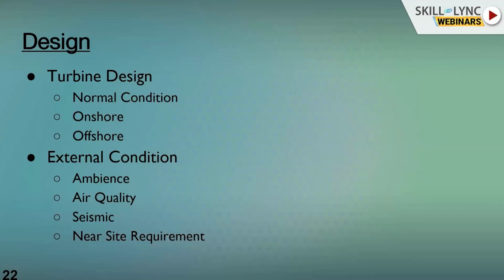If you take thermal, you can put a valve and then you can regulate and rotate the turbine at a regular speed. And if you want to stop the turbine, you can close the valve and stop the turbine. In case of hydro, you have a butterfly valve to regulate and to stop the input fluid. But here in wind, input control is not possible. All the safety measures and also control, everything the designer has to consider in the design itself.